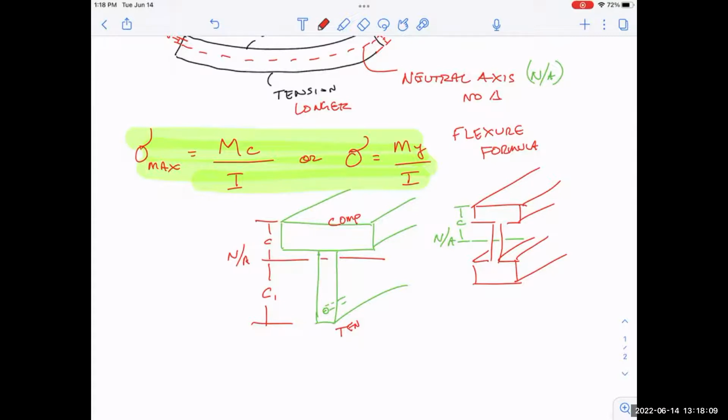And if that bends too much in the wind, the people at the top level feel sick. I mentioned in one of our classes that they even have a whole system in the top story of those to counteract that. Because you can't just build a building out of solid concrete, because it costs too much. So we want it light, but if it's light, then the wind's going to want to blow it around a lot. And so this business of something bending, flexing, that's why this formula is so profound.